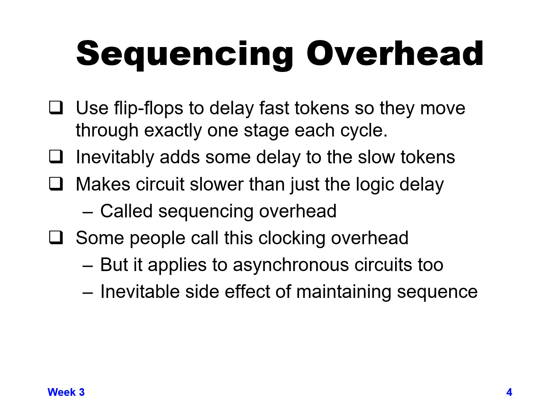They get there just before it switches, so the slow ones don't really wait, but the fast ones need to wait. So inevitably this is going to add some delay though to even the slow tokens, because you need to make sure that even the slow token gets there just before the element switches, and so you can't get it there at exactly the same time every single time such that you don't get any delay. And the flip-flop element itself takes some amount of time from its input switching to the output to switch, so there is overhead and extra delay through the sequential elements.